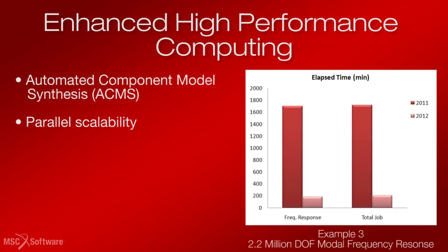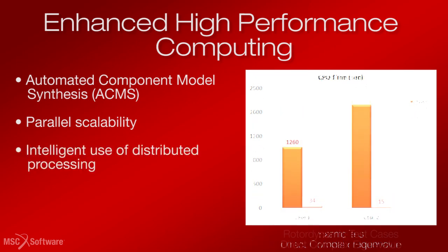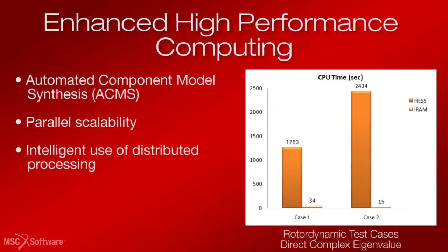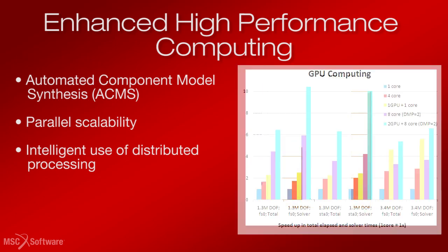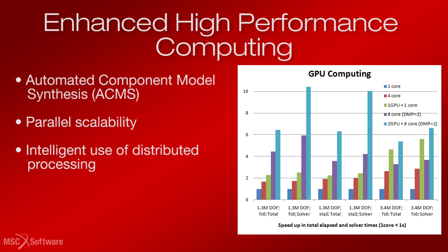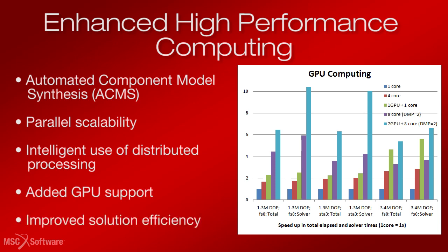Other solver enhancements include improvements to unsymmetric matrix solution and a new implicitly restarted Arnoldi method, IRAM, for complex eigenvalue solutions. In addition, MSC Nastran now takes advantage of graphic processing units, or GPUs, to improve solution efficiency. For certain problems, this feature has shown overall performance improvements of up to 5 times.